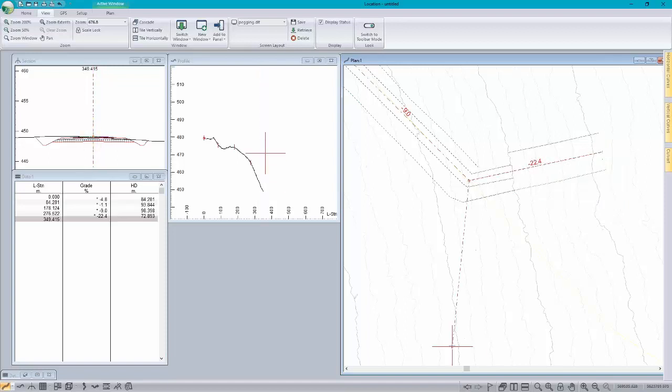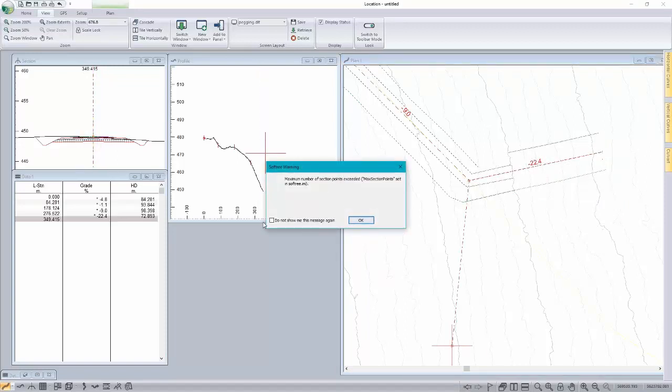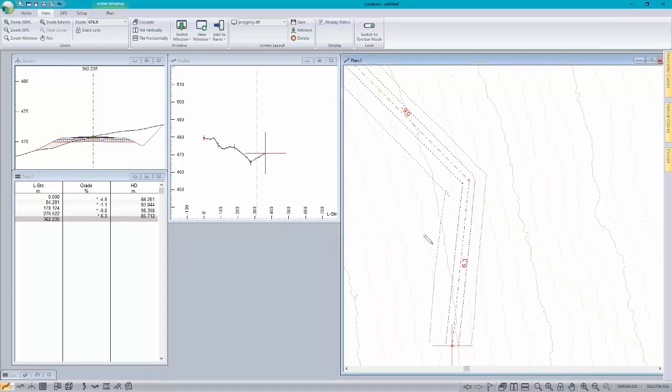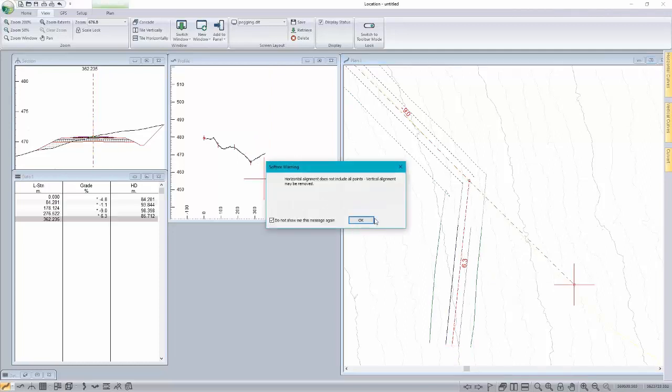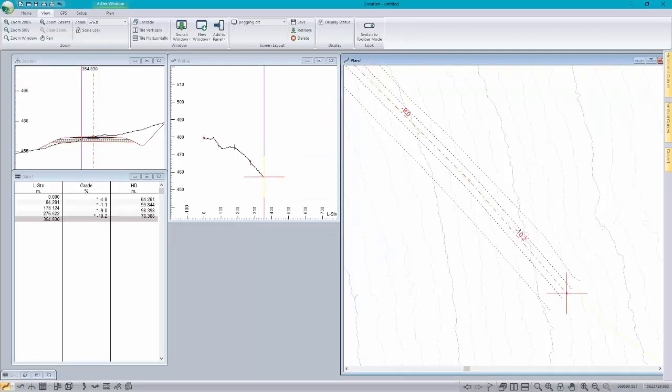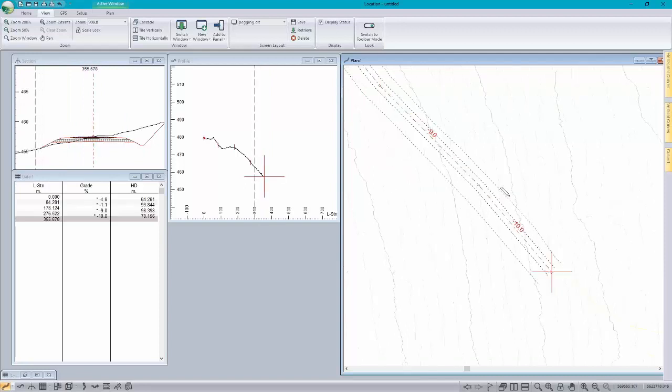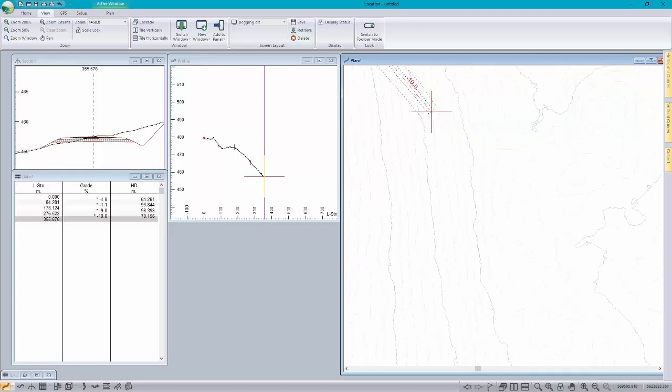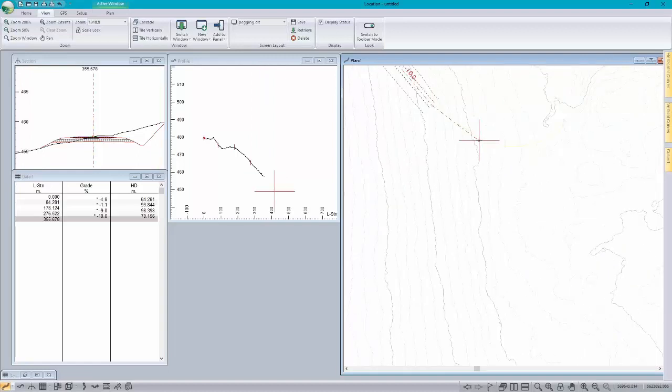If I go up the hill, of course, we're going to have a plus grade. If I follow the alignment that I have in the background, it's about 11% there. Maybe I want to keep my grades under 10. There we go, there's 10.2. A tiny bit up the hill, now it's 10.0. Some schools call this pegging.